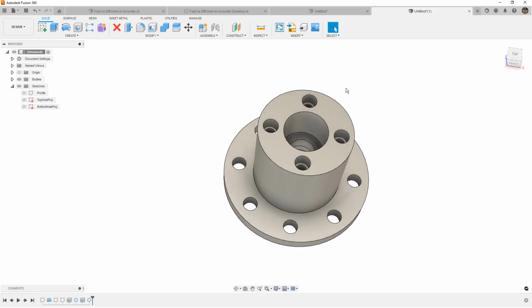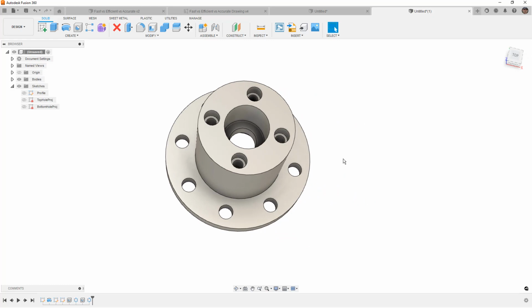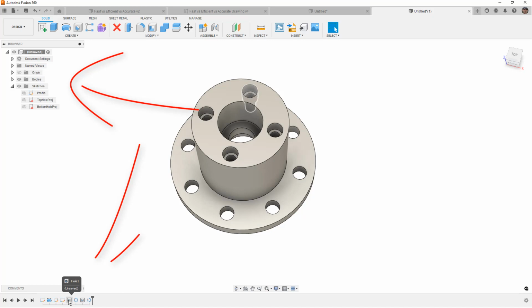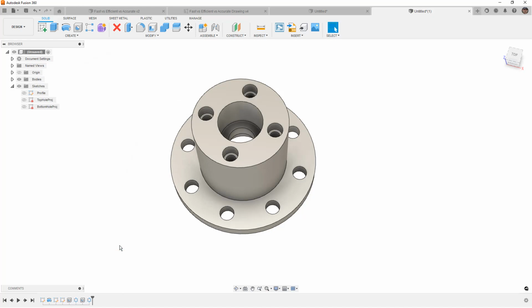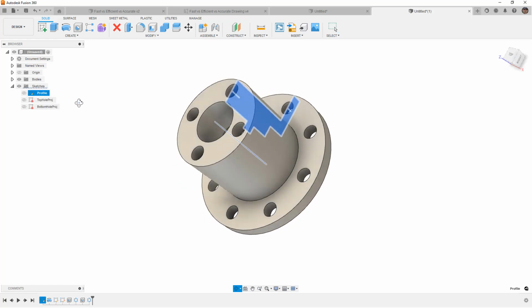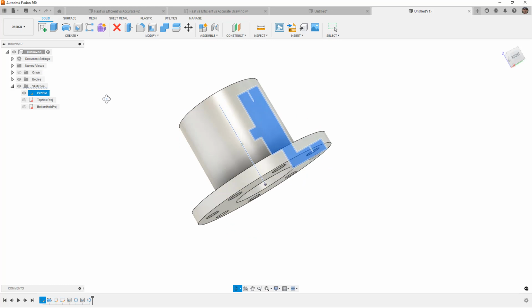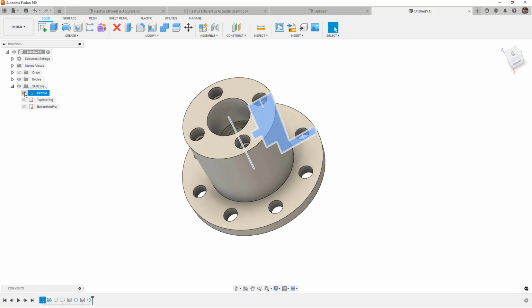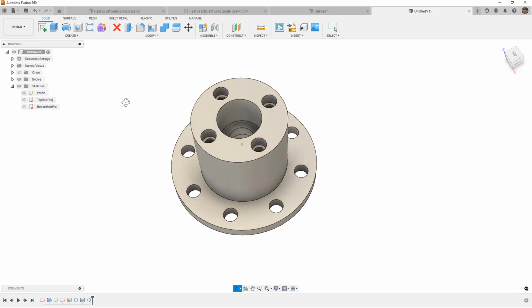So at the end of the day, really the main difference that we have here is going to be in the number of sketches, the number of features that get created, and those references. So the references are the important bit. Even though we've got 2 additional sketches here, those sketches are projected references from the original. Everything that we need in order to modify this design is contained in that first original sketch. All the detailed dimensions, all the references for the bolt hole locations, everything happens in that profile sketch. This means that this design is extremely efficient when we get to making updates for it downstream.